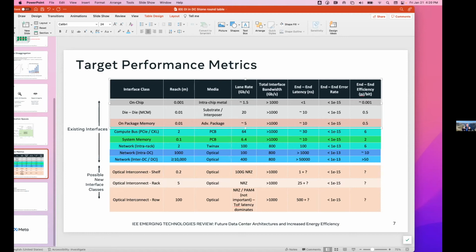Second thing is, when you do go to disaggregating the HBM, we certainly have limits. These are obvious, but the HBM is only a certain number of millimeters wide. There's a certain amount of beachfront. The bit rate on HBM is dramatically increasing on its own path, so obviously we'd have to accommodate that bandwidth in similar beachfront. And then the size of the optical solution, there certainly have to be constraints on that as well, right?